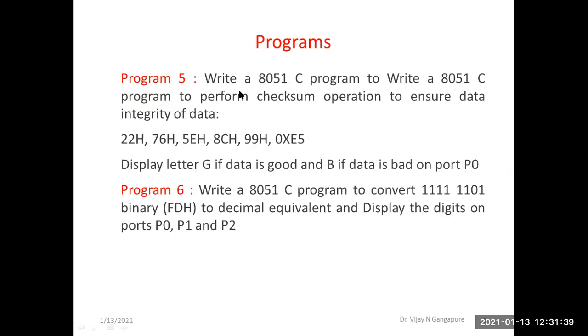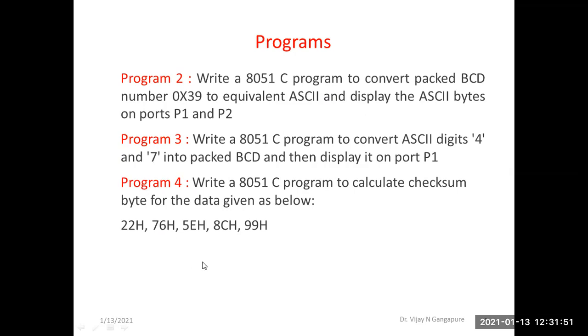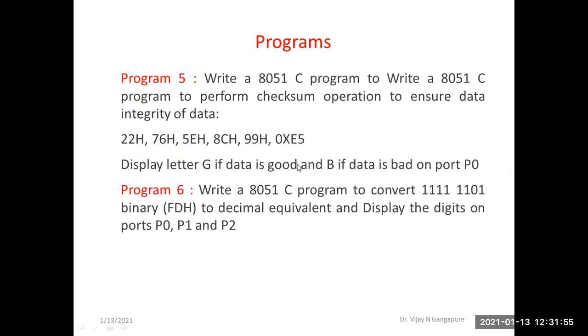Program number 5: write an 8051 C program to perform a checksum operation to ensure data integrity of the data given. The same data is given, that is 22 76 5E 8C 99, and in the end there is one more byte. This is actually the checksum byte.